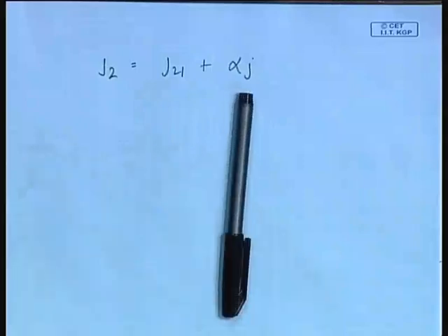Now, the first thing which I would like to tell you in this class is, when we had written down this particular expression, it assumes that J2 and J21 are constant over the entire cross sectional area, isn't it? This was the first thing that we had assumed, that we take an averaged value of these parameters, averaged over the entire cross sectional area. Now, usually we find that this can be a very drastic assumption for most flow situations. For most flow situations we find that they keep on varying across the cross section.